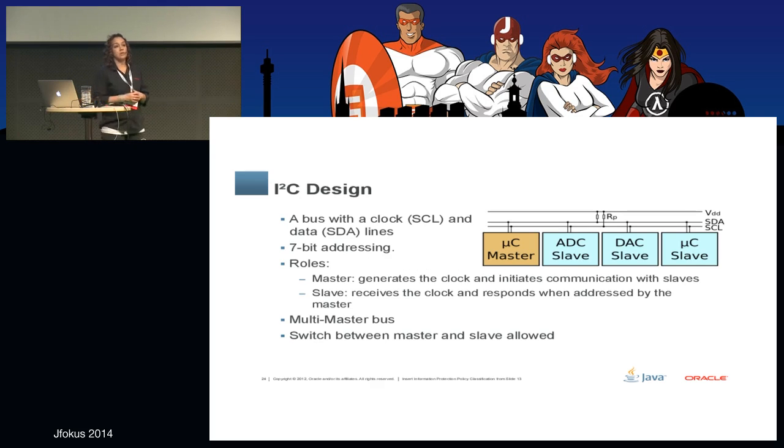This is a little bit how it looks. You have the 2 buses, and pretty much everybody hooks up into the bus. What is really good is as long as the devices have different addresses, you can connect as many as you want. That gives you a lot of flexibility, even though there are only 2 buses on the Raspberry Pi, one for data and one for clock.